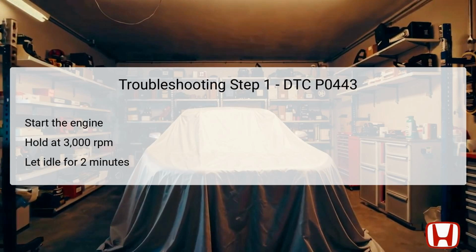Commencing the troubleshooting for DTC P0443 requires starting the engine and stabilizing it at 3,000 revolutions per minute without load. That is, with the vehicle in either Park (P) or Neutral (N) mode. Holding the engine at this RPM allows the system to reach its operating temperature, which is critical as various components need to be assessed under normal conditions.